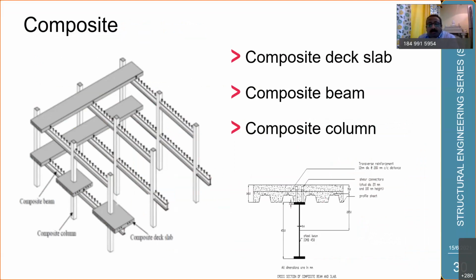And when it comes to the composite, like composite deck slab and composite beams and composite columns, most of the tools allow you to model these kinds of composite members and elements and sections. But on the design side, we are depending more on the Euro codes or other codes, not with the standards of practice. So that is what I have seen in the tools.